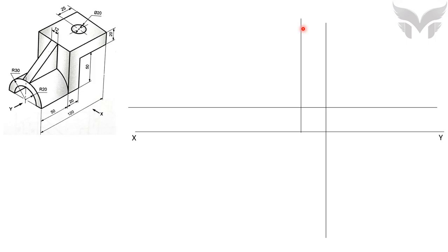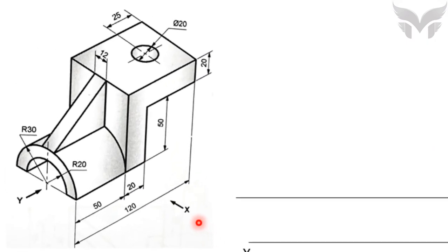Now, to know how the front view of the given object will appear to you, let's imagine that you are standing far away from the object and looking at the object from the X direction. Remember, the direction for the front view given is X. So let's observe the object part by part, meaning that initially let's keep focused on this bottom semi-cylinder having a semicircular slot inside it.